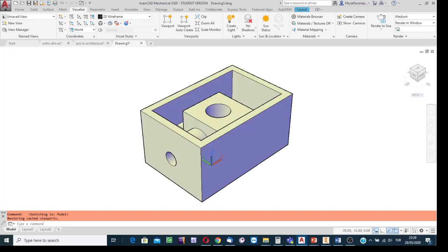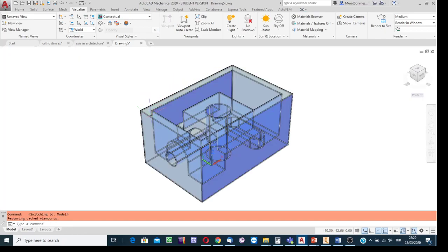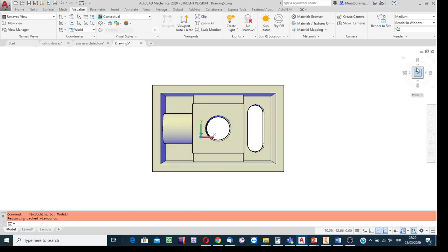In answering this question, I'm going to define this side as the top side, and observe the body in this direction for the top side view. The object is symmetric, and good practice is to cut the body at the symmetric cross section. The cutting plane in this example is going to be oriented perpendicular to the picture plane of the top side view, so on the top view we can see it edge-on. The cutting plane line can be shown on the top side view.